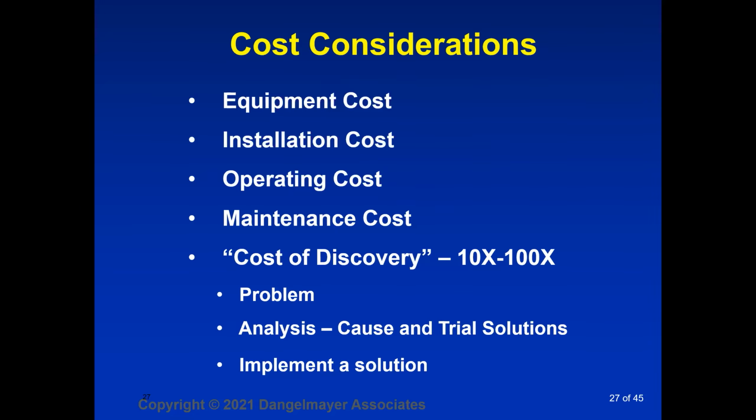The installation cost: what do you need to do to install the ionizers? Ionizers typically use a very low amount of power so that you can use many ionizers in an installation, except in the case where you have ionizers that might have heaters in them. This will increase the power consumption dramatically.